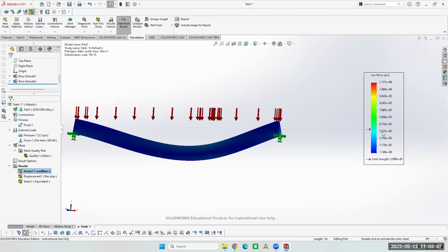I did this in 2 minutes and we did this in like 15 minutes. But it's little things like fixing the edge versus fixing the face where your confidence will go up and down. When I first ran it, I thought, that's not what we have. We have free end rotation.